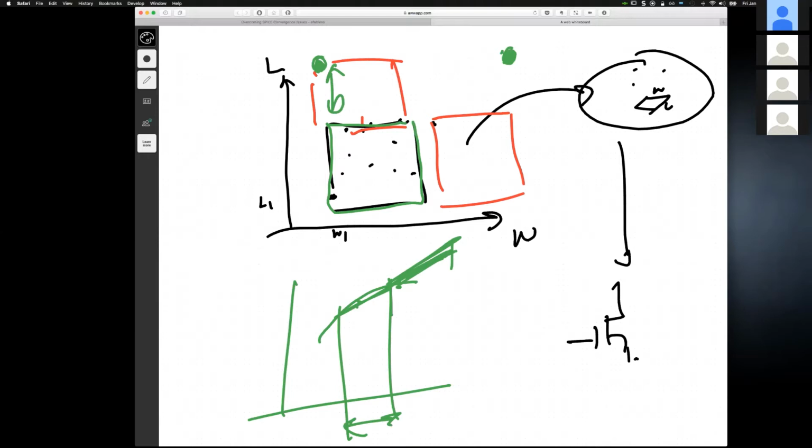Okay, but yes, I agree. But my question was: is there an actual maximum allowed size for, say, a resistor from the fab? Like, do they say don't make it larger than this? So I'll have to say the answer is yes. It's model dependent. So the answer is yes, and it depends on the process.